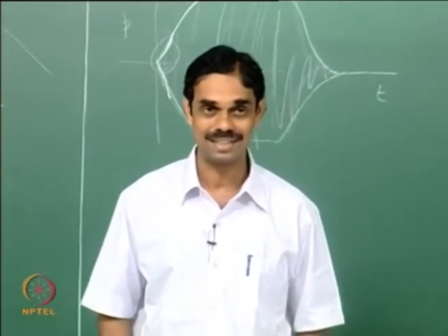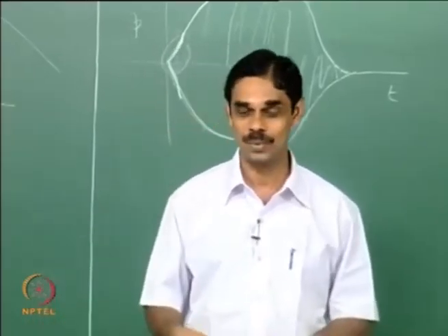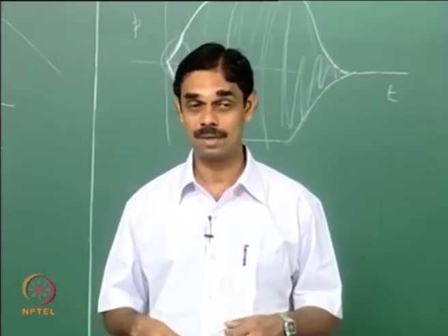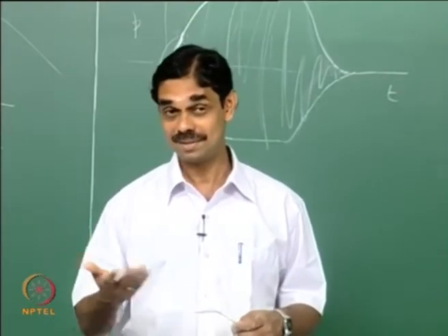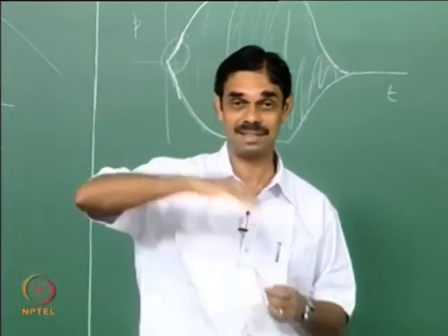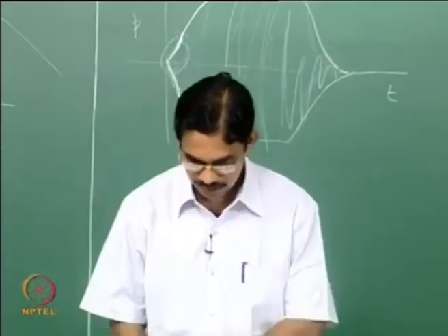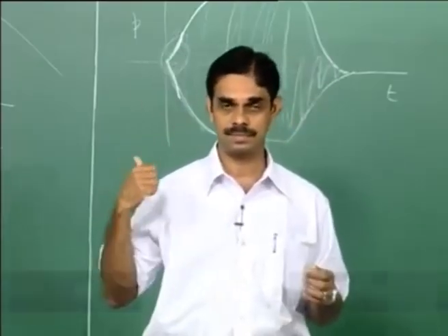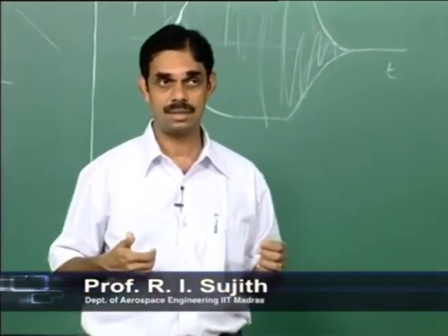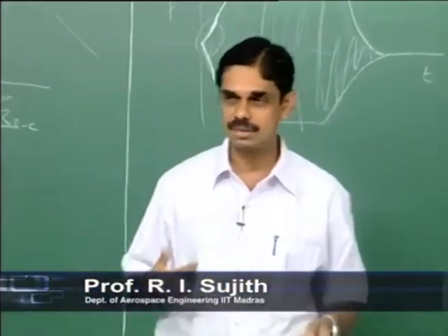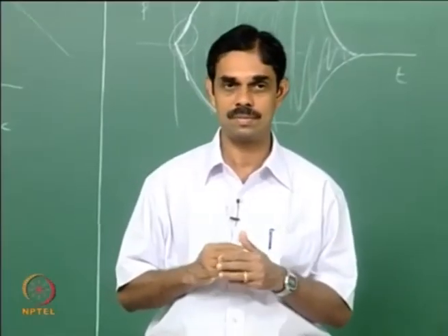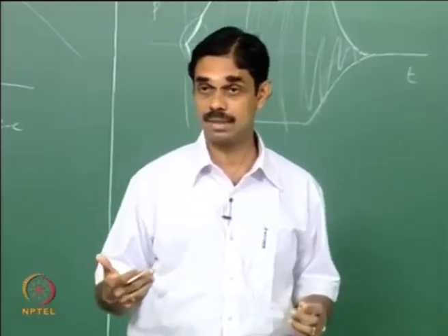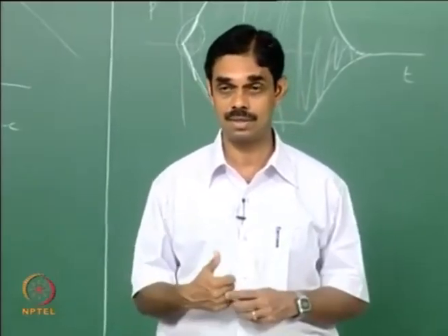So then you end up looking at this, but it will be really nice to have proper piezoelectric transducers or piezoresistive transducers put into the motor. Piezoresistive, because we saw DC shift can happen and mean pressure can elevate quite a bit. And if you are talking about a small rocket, like the air-to-air missiles or the small handheld ones, then the frequencies can be very high, because the smaller the motor the higher the frequencies. So there you have to have high frequency response transducers, and you have to have good piezoelectric transducers.